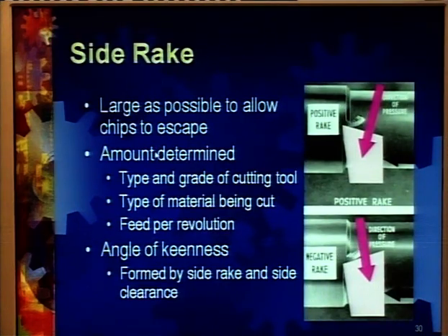We can also read out here that it should be as large as possible to allow chips to escape. Actually, it should be larger. We can also see, from common sense, that if the rake angle is larger, then this edge, which is the actual cutting edge, will be sharper, and hence the chips will flow more easily onto this particular edge.